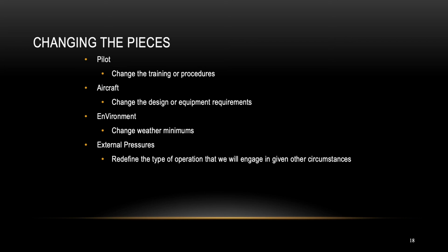On the environment, you may want to change your weather minimums. For external pressures, you may want to redefine the type of operation that you're willing to engage in, given your experience level, or come up with some way of mitigating an external pressure that caught you off guard. Regardless, the point of that process is to improve the safety over time.